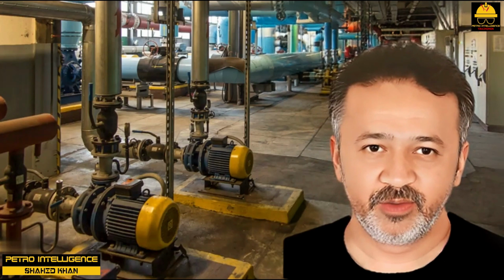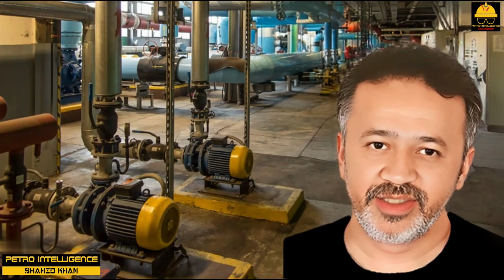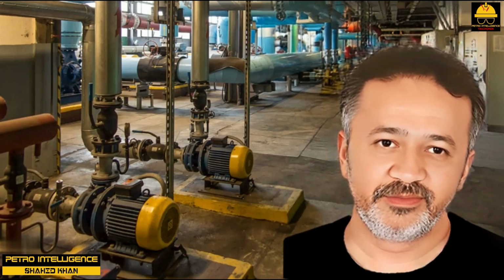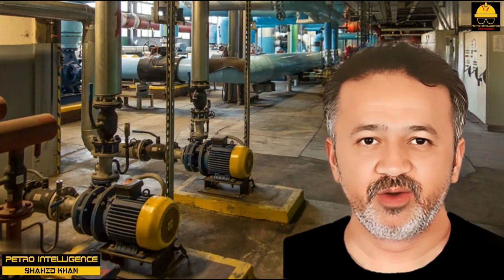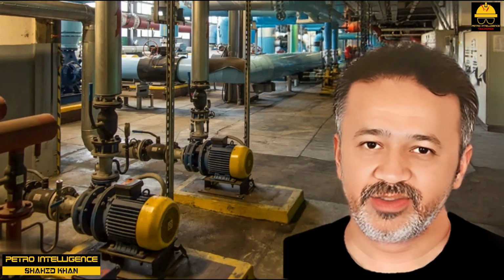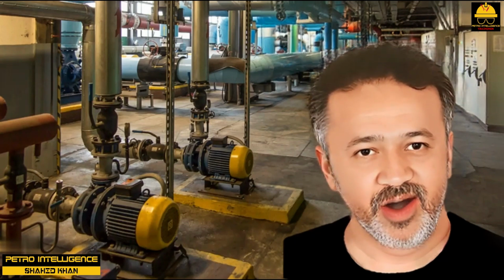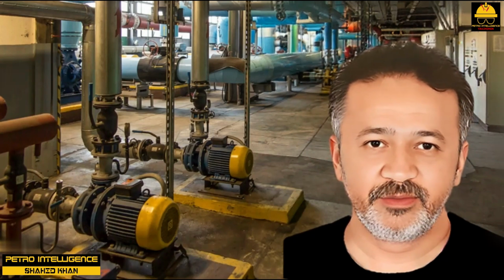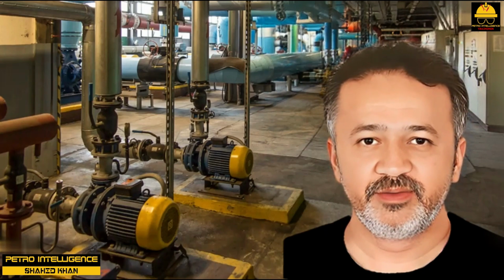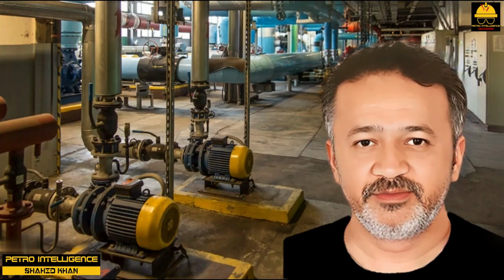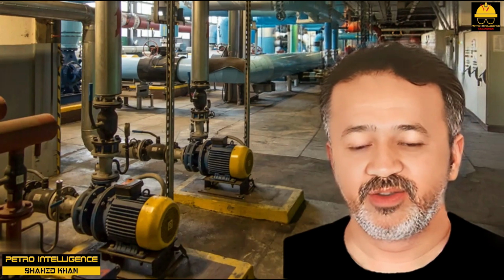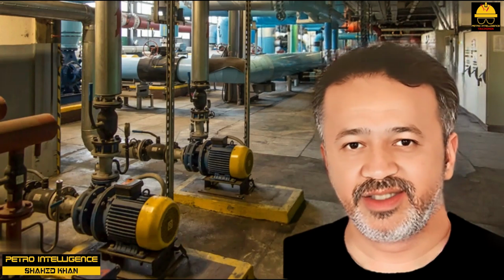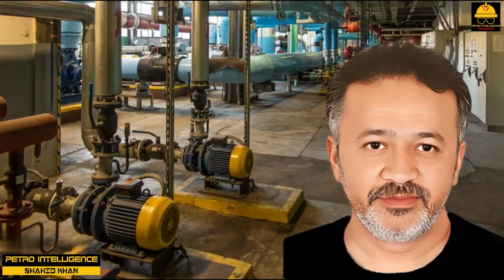A few days later, the pump briefly lost suction, due to a slightly low level in the flash drum feeding the pump. The pump cavitated, and the flow was reduced. Reducing the flow to or from a centrifugal pump reduces the horsepower load on the driver. As the steam flow to the turbine driver was fixed, the turbine started to overspeed. The excessive speed damaged the pump's bearing. The resulting vibration fractured the seal flush oil line to the pump. The flush oil ignited on the 700 degrees Fahrenheit pump case. A nearby worker was sprayed with the burning oil and killed. This is a true story.